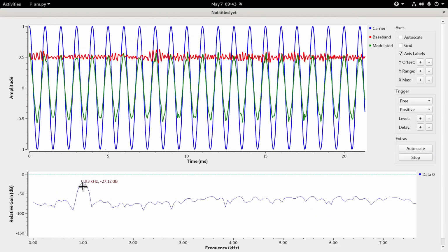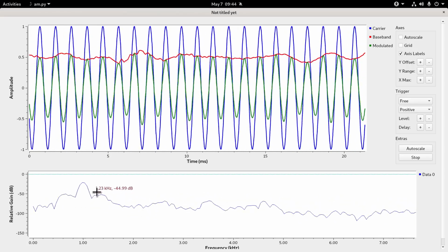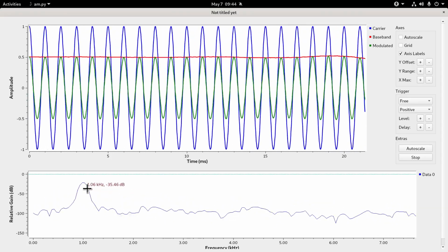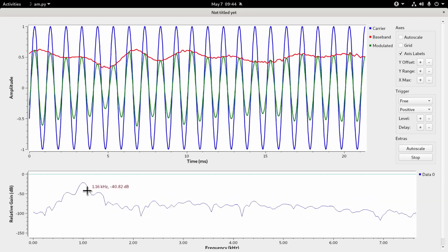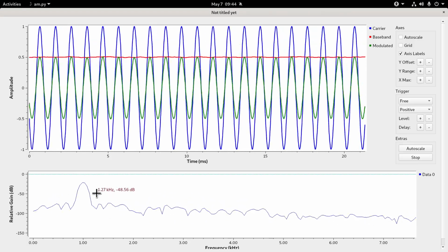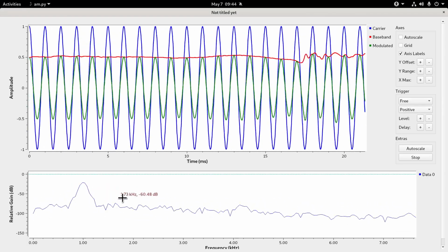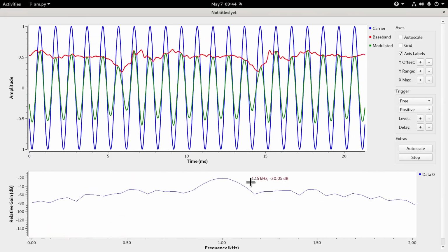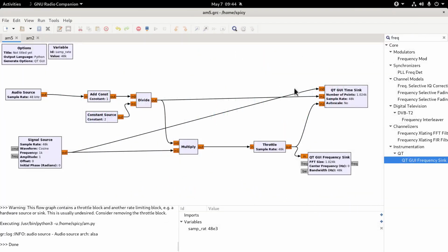So you can see the carrier frequency at 1 kilohertz. And there's extra energy here when I speak, so you can see that there's some energy on this side of it and this side, and it'll be the same, just inverted. If I try and speak really loud, I'll never match what that carrier is doing with such a high duty cycle, so I'll never get up to that. But what you can see is we have these sidebands, and it's due to the mixing, pure and simple, like I just showed. Okay, forget about all this stuff up here. Yeah, so that's basically AM, and there's its carrier with a couple of sidebands. Okay, so that's that.